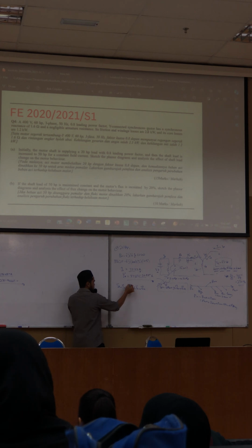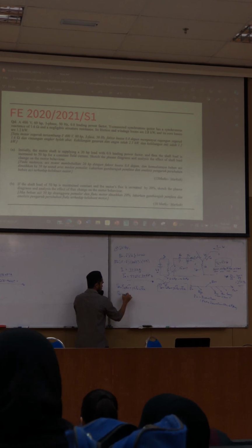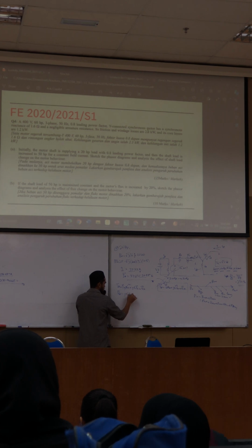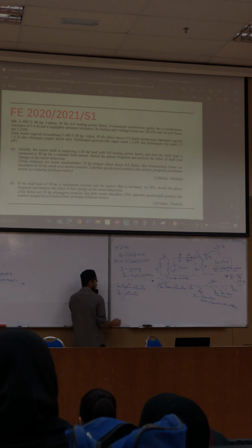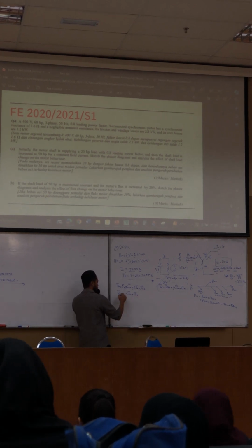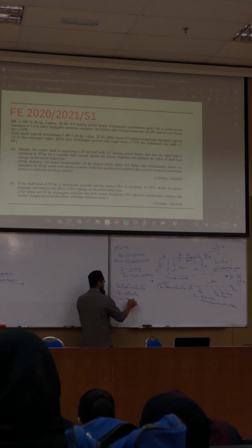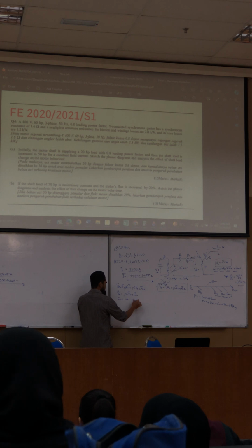So when IA RA is neglected, it remains V phase equals jXS IA plus EA. Then your unknown is EA. And so EA, putting this to the other side, becomes EA equals V phase minus jXS IA.